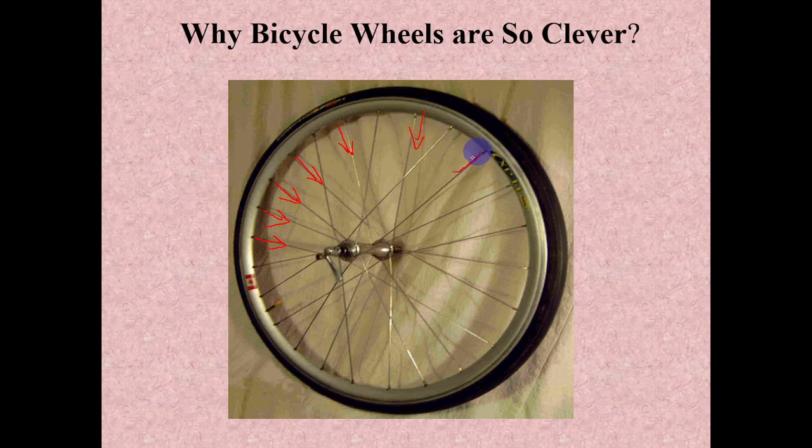When a circular arch is subjected to a uniformly distributed radial load like this, it will have pure thrust in this arch portion. It will not have any tension or any bending at all here. So that is how it works. That is why it is called a wonderful invention.